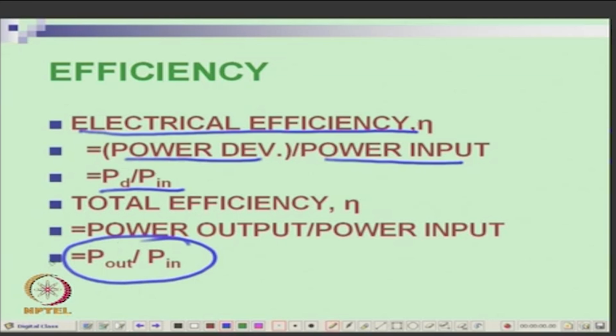This is a simple thing, whatever is the electrical power divided by mechanical power. Now, what is the reactive power? Q input will be 3 times Vs Is sin phi s. If S is the volt amperes at the grid, that is 3 Vs Is, the electrical power will be S cos phi, which is negative because phi is more than 90 degrees, but Q is S sin phi, which is positive. This is the power taken out of the grid and Q taken out of the grid.